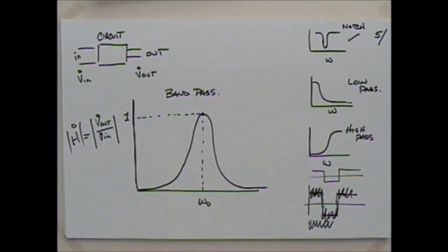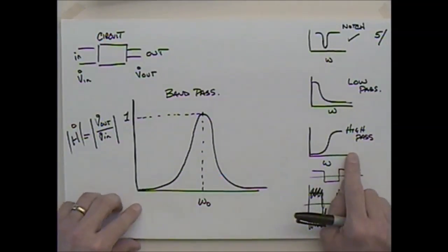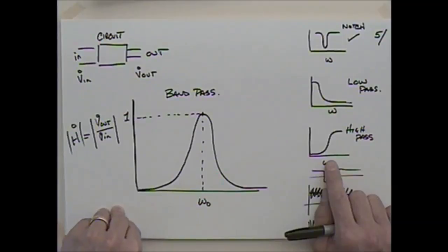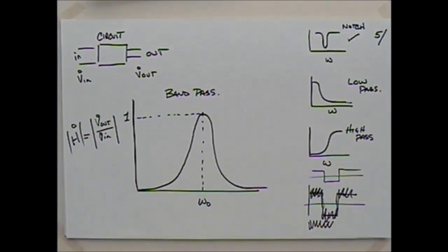What are those events, though? Those are low frequency. So if I ran my measurements on the window vibrating through a high-pass filter, I would stop all of that low-frequency noise that I don't want, the doors opening, the heating and cooling coming on and off, and I'd just get the high-frequency voices, wouldn't I? Yes? Why is it that a voice is a high frequency and other voices is low? Well, I'm not necessarily talking about noise, but rather events. Whether the door makes a noise or not when it closes, it causes a pressure in here that will cause the windows to vibrate. It just doesn't happen as fast or as much.